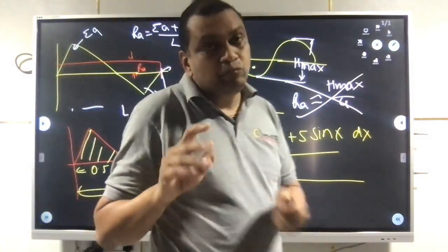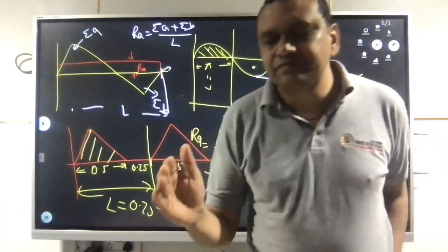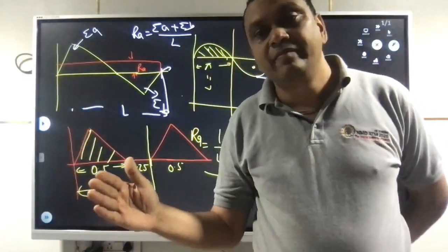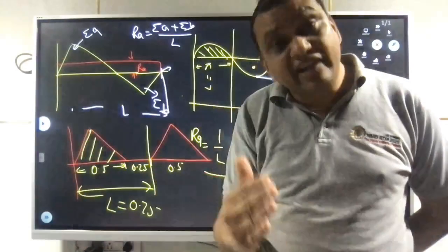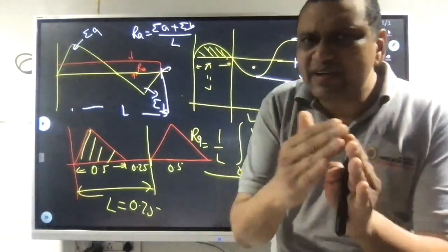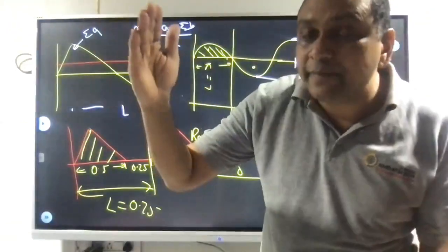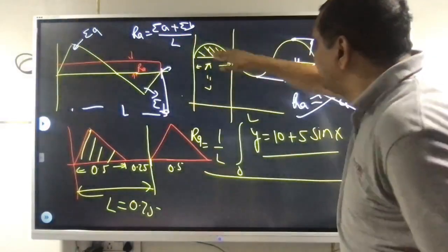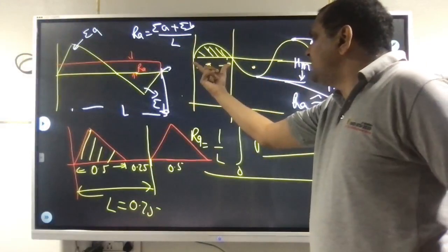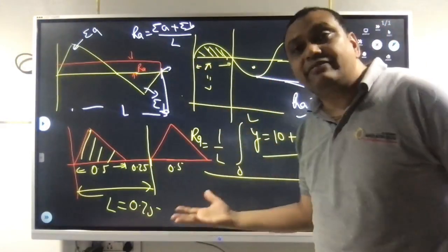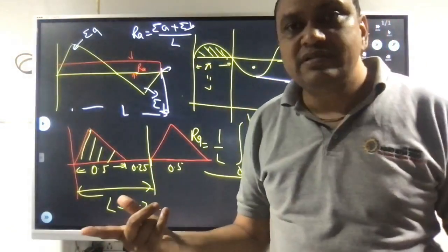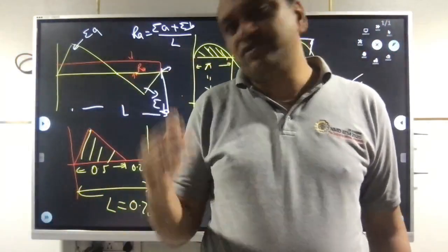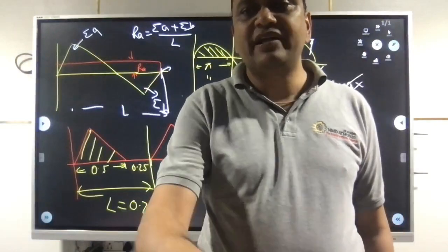Once again, in such types of problems, either the cutoff length will be given to you, or if it is not given, from wherever the sequence of events is repeating, you can take that as the cutoff length. In a sinusoidal curve, because the area above and below are the same, if you integrate along this pi, that will also give you CLA. So this is one problem. There are many problems. I will let you know all these things over a period of time. Thank you very much.